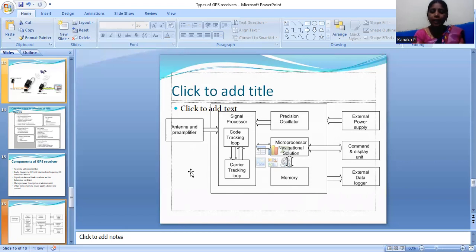The standard transit electronic theodolite is basically a telescope with a crosshair for sighting a target. North is 0 degrees, relative to the angle of inclination of the telescope. Then the electronic distance measurement transmits an infrared beam, which is reflected back to the unit with the help of the prism. So EDM applies timing measurements to calculate the distance traveled by the beam. The main requirement for EDM measurements is a reflective target, which is usually achieved by the use of a reflective prism.